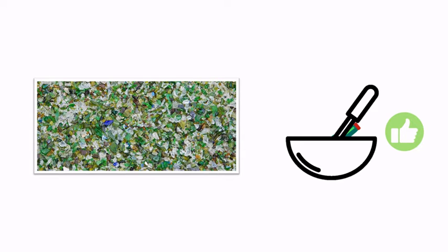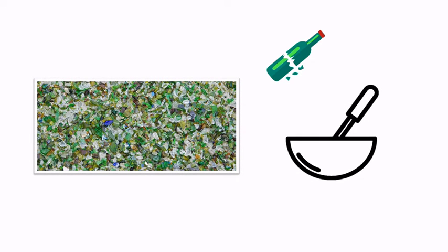The soda ash makes melting easier, the limestone adds durability, and the dolomite adds working and weathering properties. Also, recycled glass is an important component for this first stage, since by being added, it greatly facilitates the process.